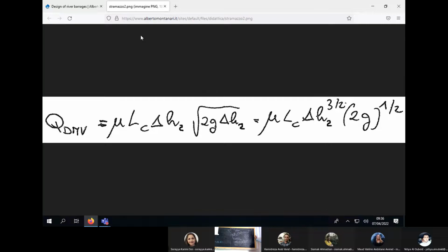So the whole rationale here is to make sure through this computation that I'm not diverting any water. I am locating the diversion spillway at an elevation such that I'm not diverting any water until there is the environmental flow passing through the environmental flow spillway. This is the whole rationale.